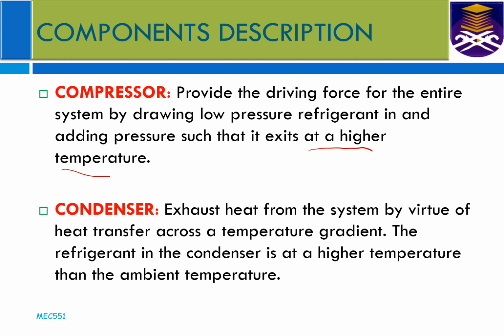A condenser exhausts the heat from the system by virtue of heat transfer across the temperature gradient. We have gone through the fourth chapter before, which is the heat exchanger chapter. So the condenser and the evaporator use the principle of the heat exchanging process.